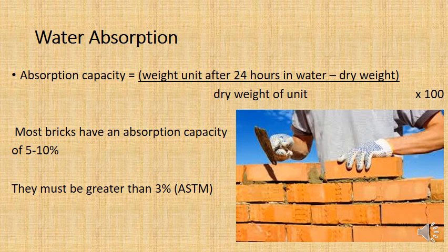Now, generally the standard from ASTM is that you soak it for 24 hours for clay oven bricks. But anyway, most bricks will have an absorption capacity of about 5 to 10%. So remember, on one side of the coin, absorption capacity and porosity is a bad thing. Basically, water can get into the brick and break it down, and so the brick will slowly, through the years, disintegrate.